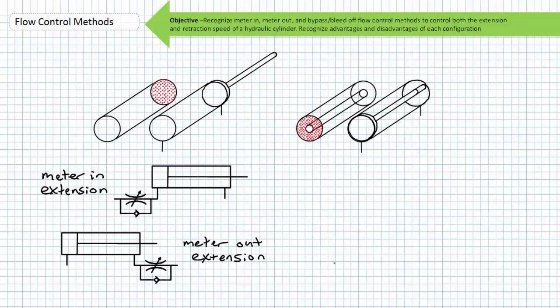The output side takes a little bit of visualization to understand. If you've been actively involved in a hardware lab supporting these lectures, you've probably run across an occasion where a double-acting cylinder with a blocked rod end port would not extend. The reason is that the fluid trapped inside the rod end volume has no place to go and is incompressible. Therefore, the cylinder, for all intents and purposes, has reached the limits of its travel early, and pressure rises until the pressure relief valve is actuated.